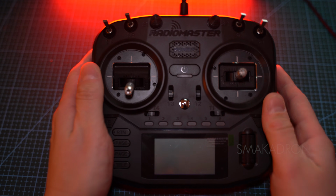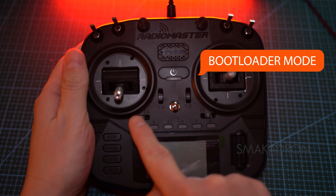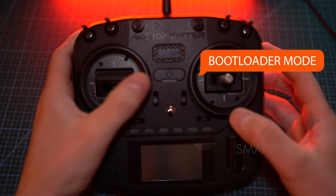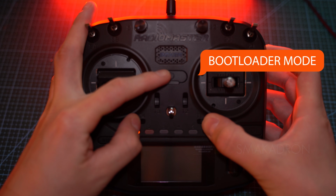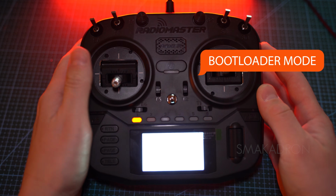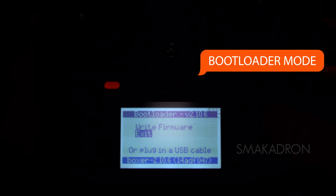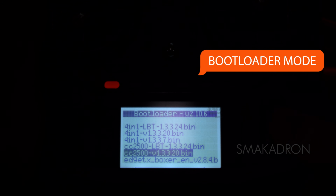Now, pay attention. We need to put the radio transmitter into bootloader mode. To do this, you need to bring the two horizontal trimmers towards each other and, at the same time, press the power button. Using the scroll wheel, select Write Firmware from the list. Then, from the list, select our firmware version.